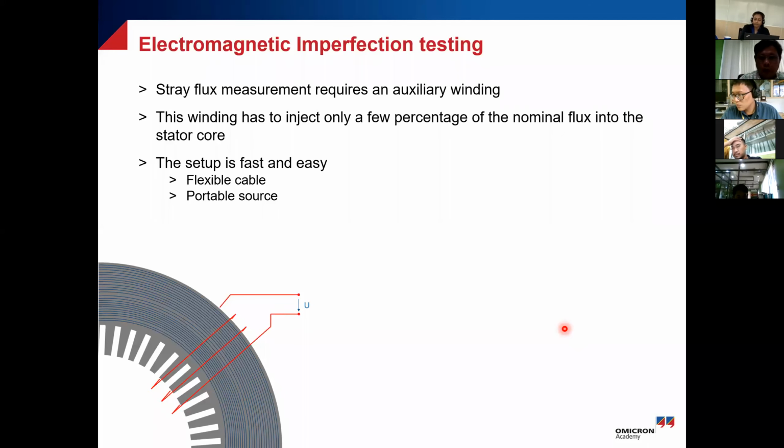And the problem, I would say, is the safety, because you are energizing it at rated flux, and then you have to go near it to see it through a thermographic imaging camera. It's not really safe. And the other problem is that because you need rated flux, you need a very big source in order to energize it. I remember we did it in the field, and we needed another transformer, to have a generator, have a transformer, and then give it voltage. So you need a big source for that.